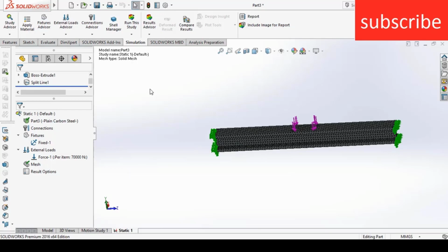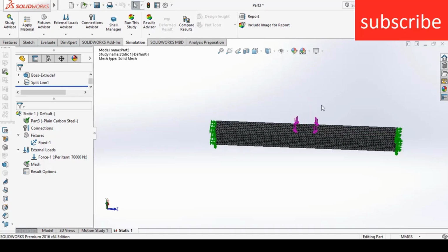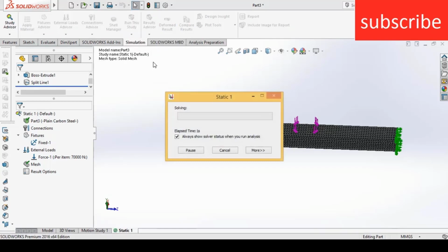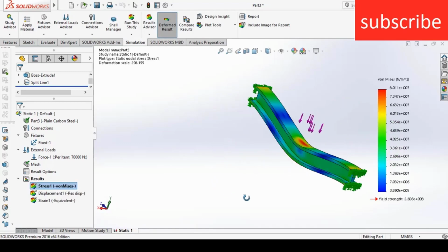And remember one thing, the higher the mesh rate, the higher will be the quality of your result, but it will also increase your simulation time etc. So I'm not going to do that. I'm just simply going to show you how to do that and how to plot graphs and other things in SolidWorks static simulation. Now click on run this study. When you run this study, what is basically happening is that it calculates. Now here you see the graph.